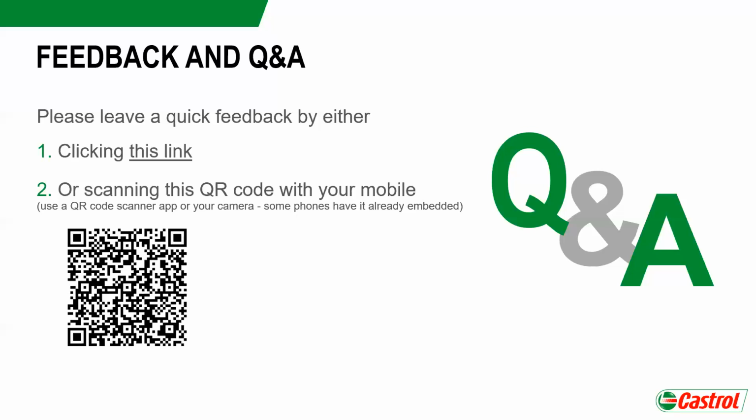You can purchase USB-stick-like devices that monitor temperature, and you can set them up from a laptop with maybe 1 minute intervals. Leave one on top of the gearbox, collect it perhaps 6 months later, and that will give you your baseline readings. Same with clip-on ammeters. You can find devices that you may have on site already that you can use to monitor that sort of performance and then compare with afterwards.